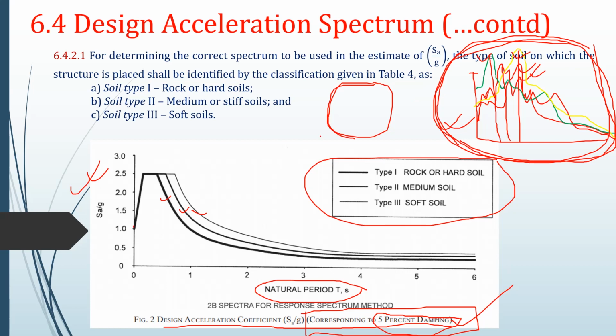And what happens if we have no past earthquakes recorded at that site? Then we have to perform statistical analysis of ground motions at that particular site. And that statistical analysis includes different parameters such as the magnitude of the earthquake, the distance of that site from the fault zone, the faulting mechanism, the local site conditions of the soil, and the geology of the travel path of seismic waves from the source to the site.